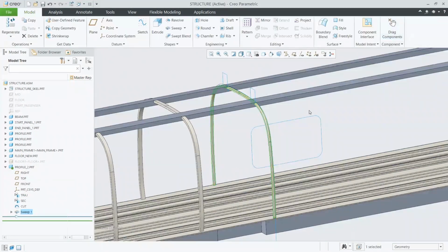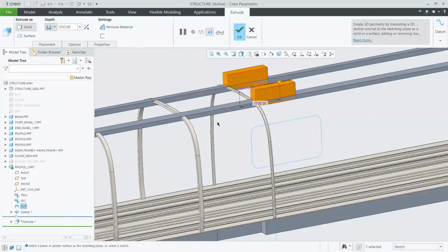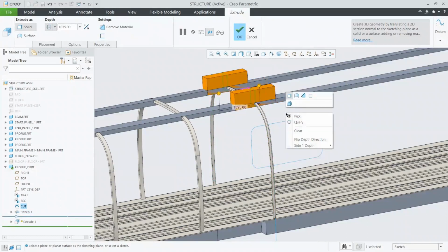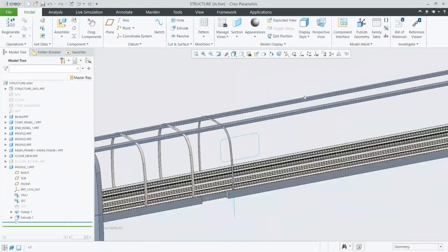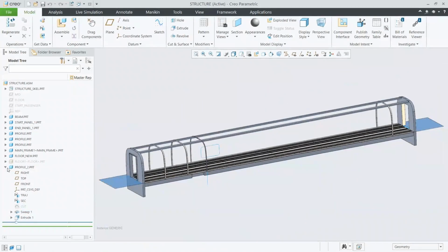And from there, it's really just standard Creo work. Cut out where the upper support structure goes, shell out to a different shape, whatever you're going to do, just some standard CAD work. And the idea still is that the master overall shape is being controlled from that top level skeleton geometry. And that's what Advanced Assembly is all about.